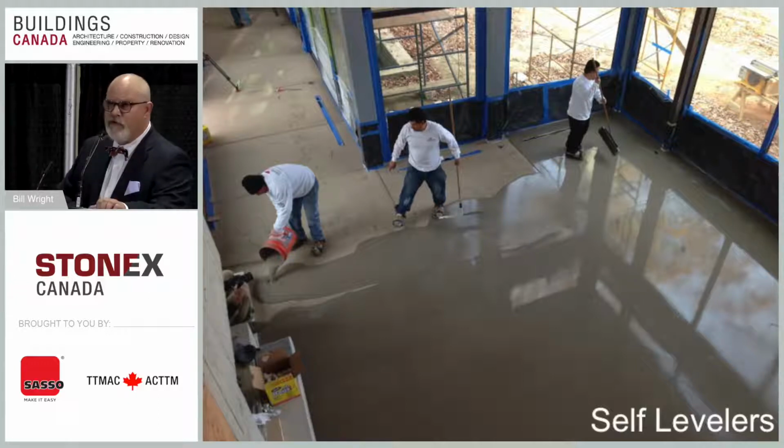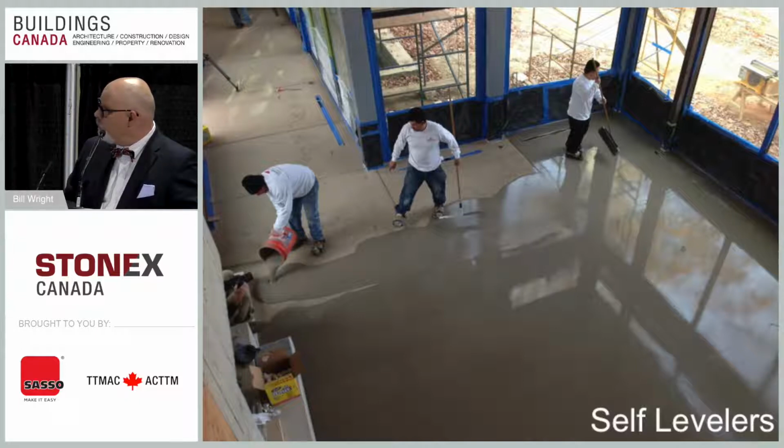And a lot of these things dry either overnight or they dry, depending on how far you build it up, anywhere from a half an hour to a couple hours. Often they'll do it the night before, so it has a chance to cure overnight without anybody walking on it, and start putting down the tile or the stones afterwards.